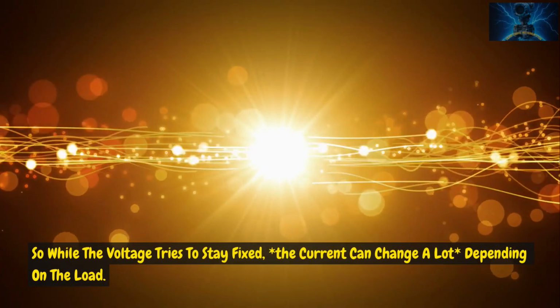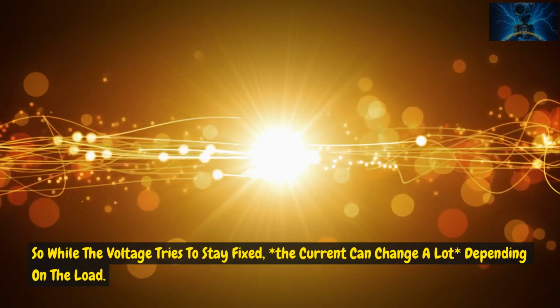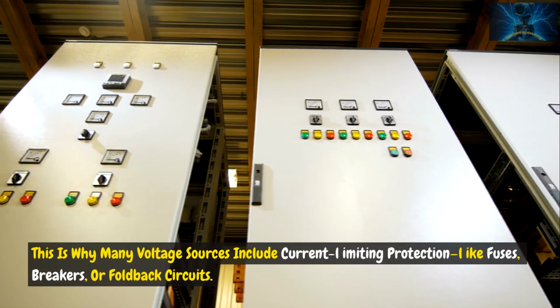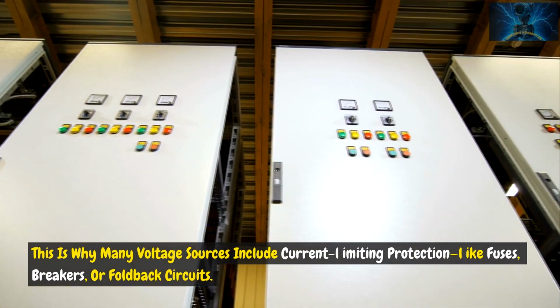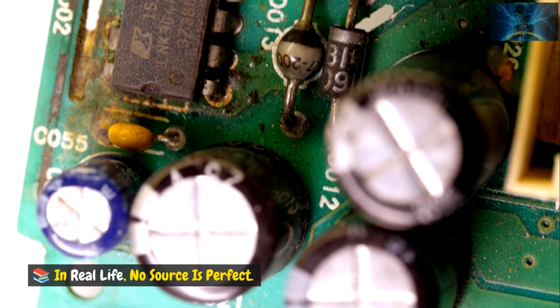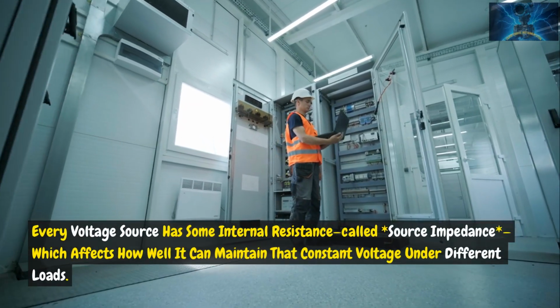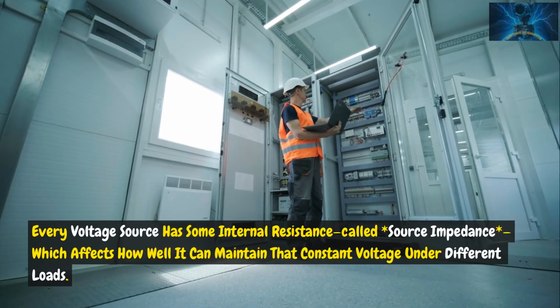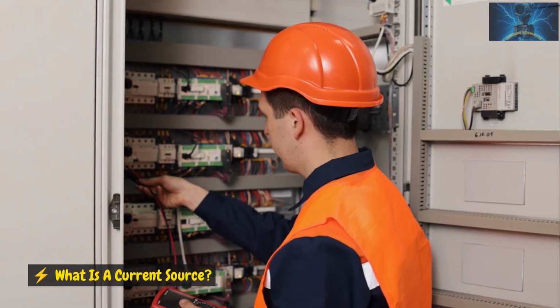So while the voltage tries to stay fixed, the current can change a lot, depending on the load. This is why many voltage sources include current-limiting protection, like fuses, breakers, or foldback circuits. In real life, no source is perfect. Every voltage source has some internal resistance, called source impedance, which affects how well it can maintain that constant voltage under different loads.